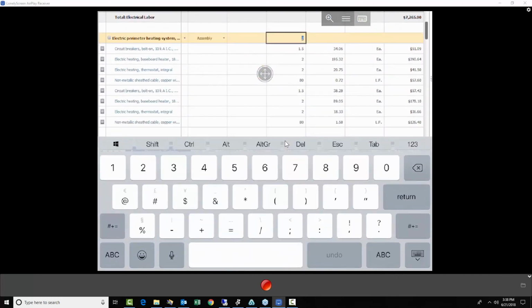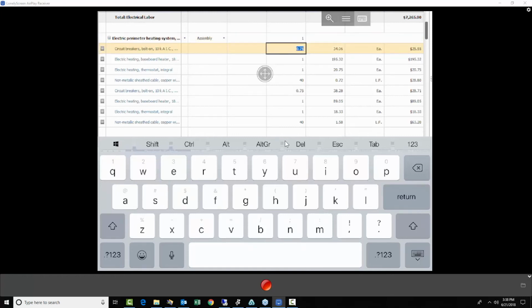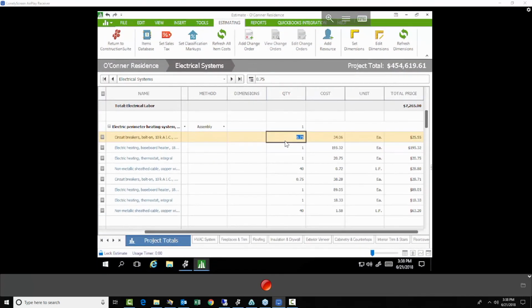Now this is very different for those of you guys who have worked in ConstructionSuite in the past. The early versions of the cost books and the assemblies would traditionally require that you insert the assembly, and then if you needed to do an update, you delete that subcategory and reinsert the assembly with the new quantity and so on. This is old news. The new tools allow you to go through and just update the quantities for the assemblies here. Now this doesn't require that you build the assemblies or insert them from the cost books.